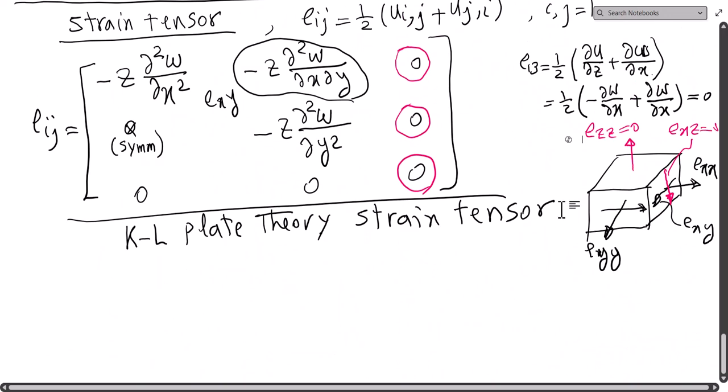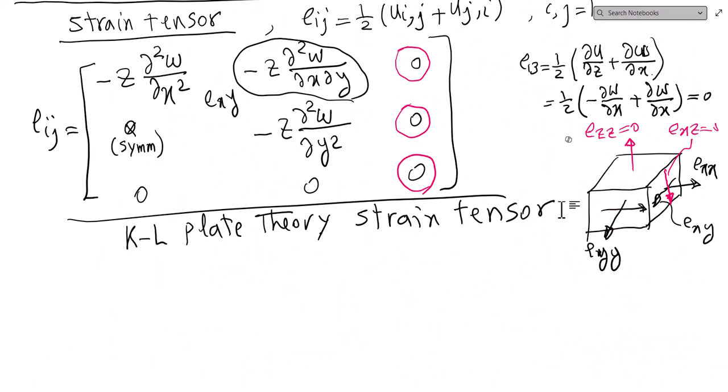That's okay as long as we assume that these shear stresses are negligible, because of the thinness of the plate compared to other dimensions. We can ignore the magnitude of this shear and its effects on deflection. That's one thing. Second is that we cannot ignore them because of the requirement for equilibrium, which we will get to later.